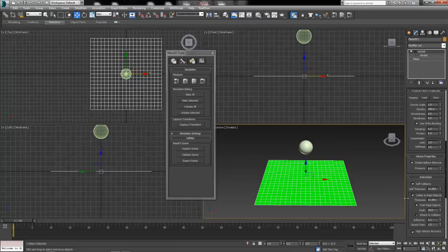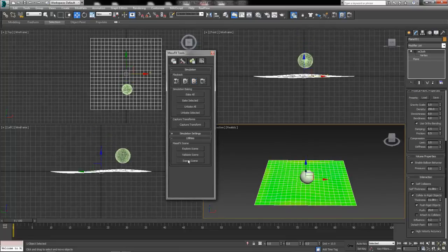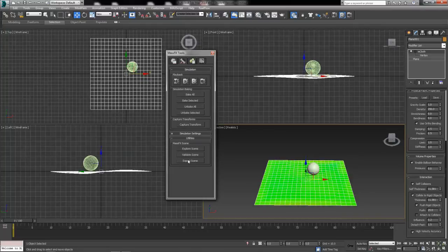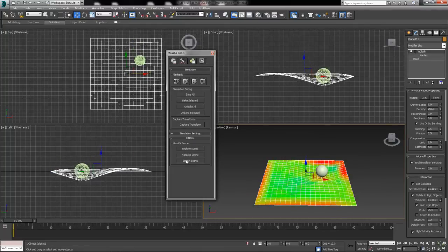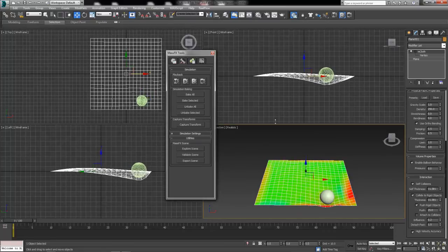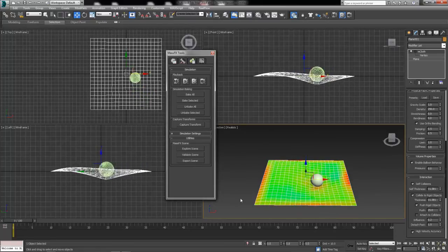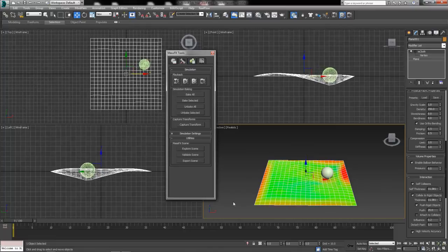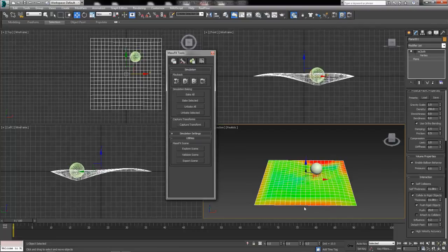If we enable the balloon behavior and adjust this pressure value, we can get some different results. At a pressure of 0, let's see what happens. We have this thing happening a little bit more. It acts more like a cushion or a pillow, and as pressure gets applied on one section, air gets pushed up in another. So this is much nicer for things like mattresses, cushions, pillows, anything that's going to have some air on the inside of it that's going to want to give.